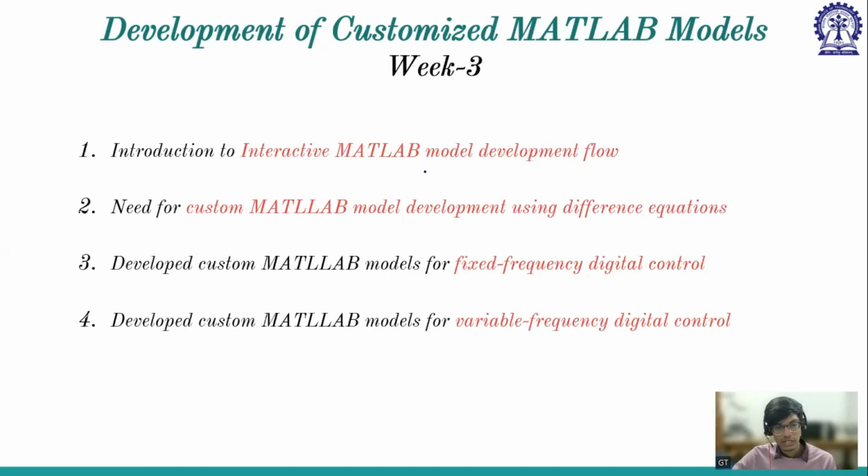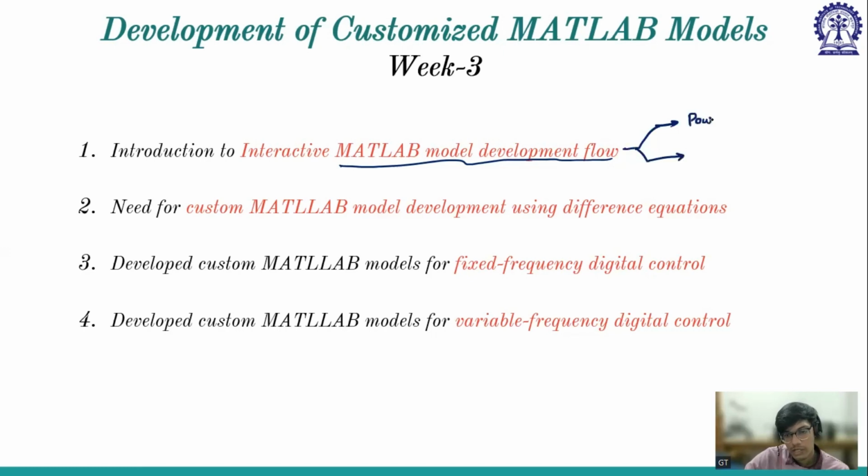In week 3, as we discussed, it is more of MATLAB models. So we started with the MATLAB model development flow. All the models have the same skeleton: one is the power stage, and the other one is the controller stage. The power stage remains the same, which happens to be a buck converter in this course, but it can change depending upon the application where you are working. Accordingly, the controller has to be tuned, and the power stage remains the same for your application.